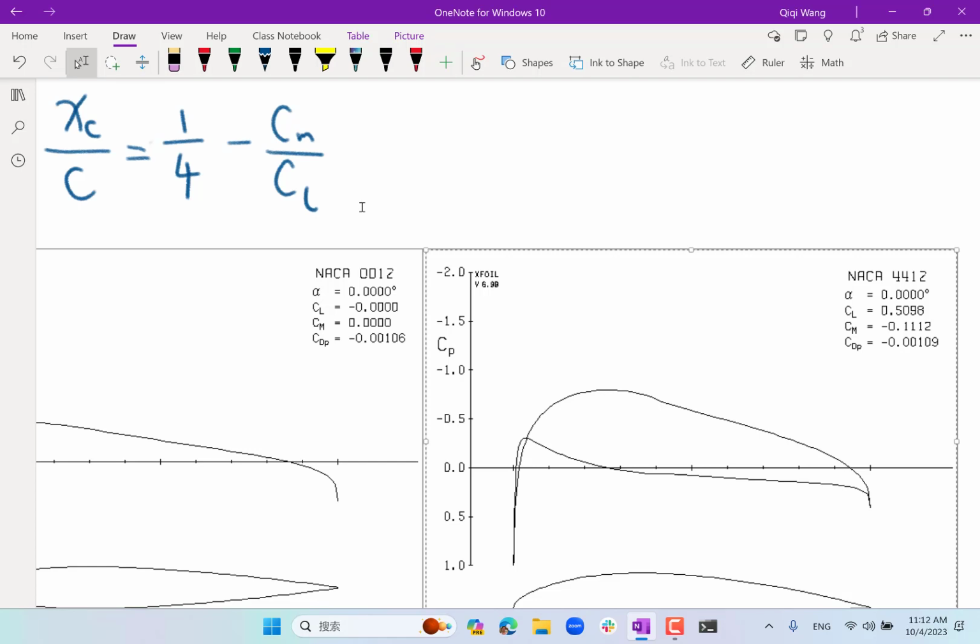Yeah, so right now, I'm asking you to compute the center of lift for this airfoil at CL equal to 0.4 and CL equal to 0.5. Particularly, I want to know how the center of lift changes as I increase my CL by increasing my angle of attack. We already said that for a symmetric airfoil, the center of lift doesn't change as I increase my angle of attack. It stays at the quarter chord. So for CL 0.4, I got 0.528, and for 0.5, I got 0.4224.